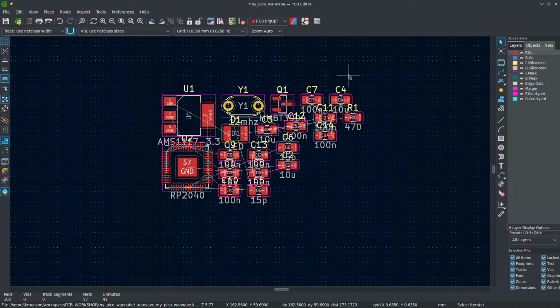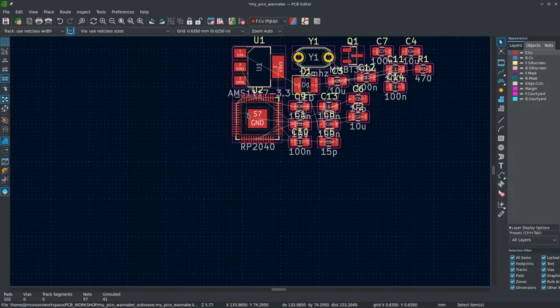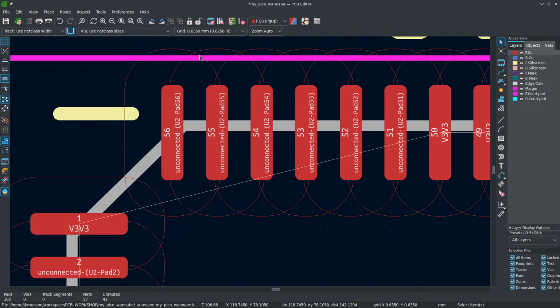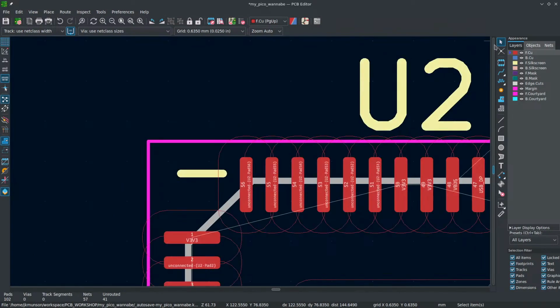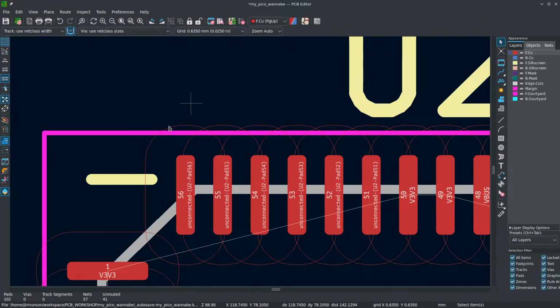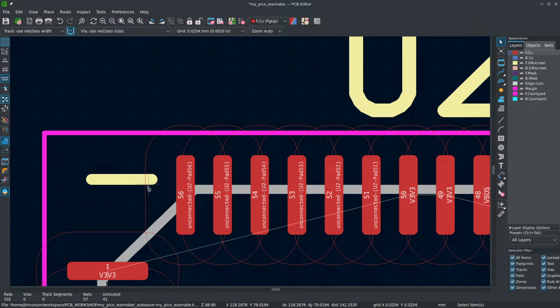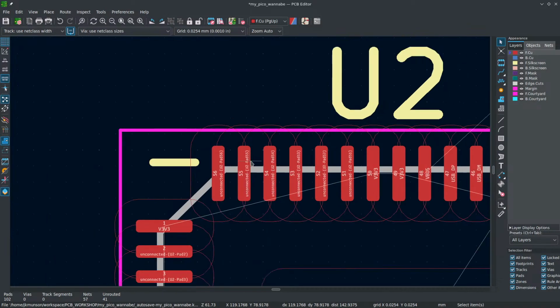And yeah, I don't want to go too much over, but I just want to point out real quick, on the designs here, all these pins on this thing have a red circle around them, which is the solder mask removal. So that's what you're looking at, since I've talked about solder mask a lot today. I wish you could see my mouse. Yeah, we can see it. You can see the crosshair now. So this right here is the solder mask removal window. It automatically removes solder mask inside of that with the default clearance.